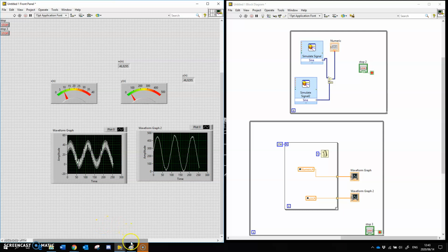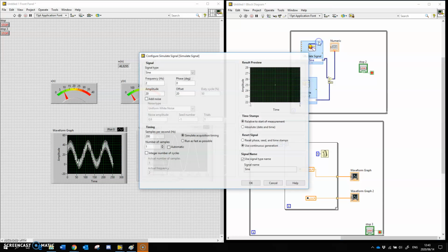Alright, so we've talked about the quantization. If we use, let's say, the LM35 sensor, it means we won't get 0 to 40. We will get 0 to 0.4. So if the amplitude here we make 0 to 0.2 with an offset of 0.2, it means we're going to go now from 0 to 0.4. So this is theoretically what we'll get.